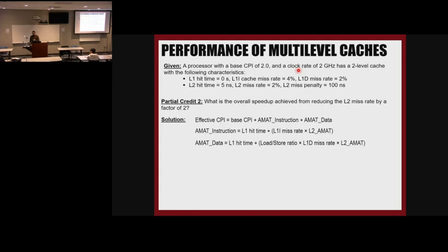Or something about instructions. Because you might just assume that you calculate the CPI and compare the CPI, which is good, but you have to keep in mind that clock frequency matters too. In this question, you're lucky because the clock frequency is not changing and the instructions are not changing. It means that we can just compare the CPI of the old design and the CPI of the new design to get the speedup. And that would be enough.